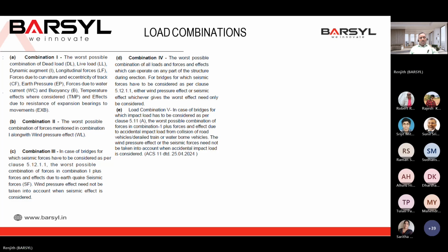Now the loads are taken: dead load, SIDL, curvature load, buoyancy effect, wind load, friction forces. All these loads are listed, calculated, and applied in the model. And after that, the loads need to be combined. So combination is based on the combination rule.